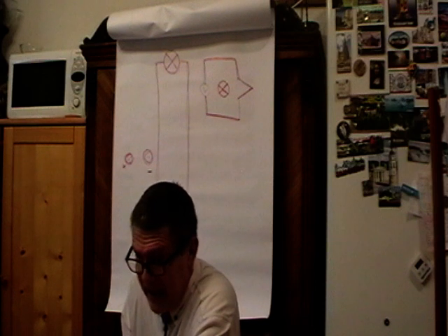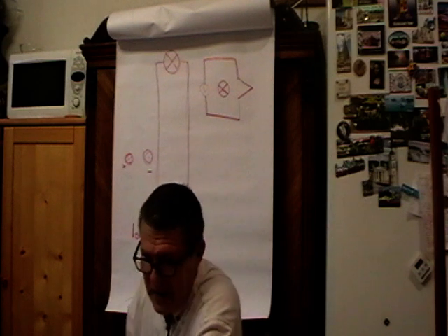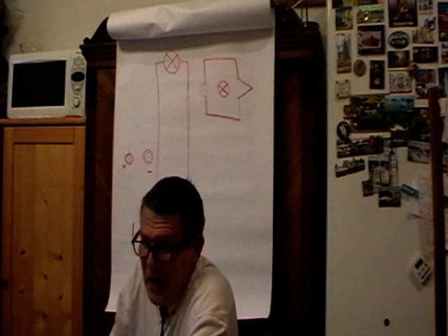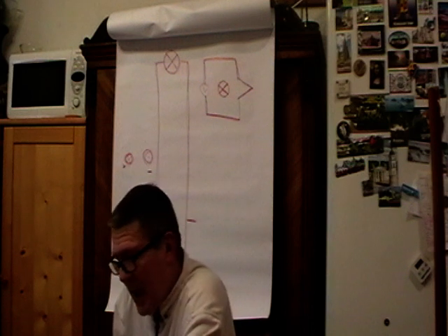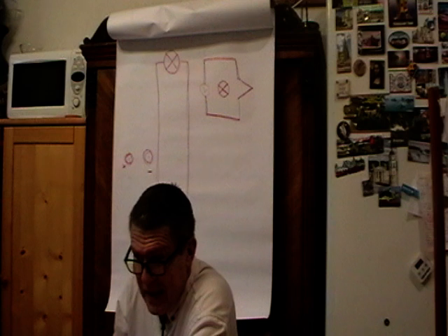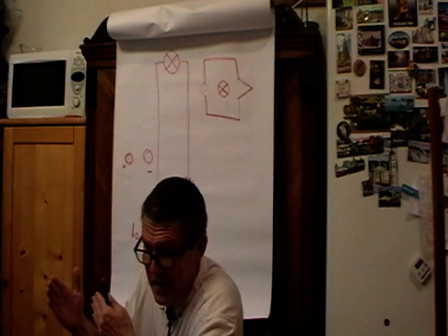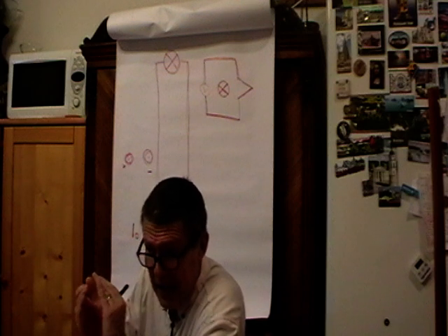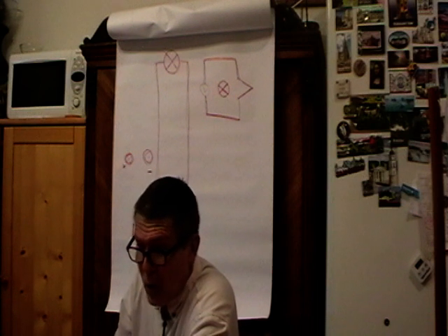On what? Well, if you have a DC circuit, and it's not a very strange one, you can forget it quite easily. If you have a low frequency circuit, you might have the chance to forget it as far as the length of the line, the dimension of the system, or the dimension of the element is small enough when compared to wavelength.